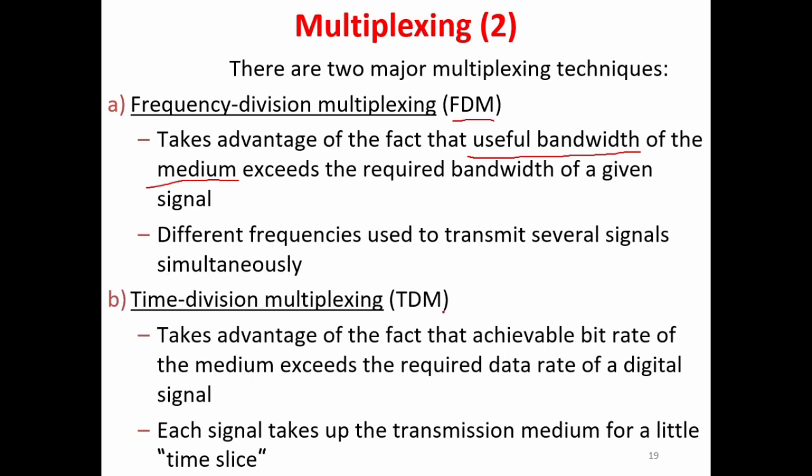But the second one, which is very common, especially in mobile networks, is TDM, which is time division multiplexing. The first one was frequency, but here we have time division. Instead of working with frequency, it works with different times, sampling the time with some notion of clocks.